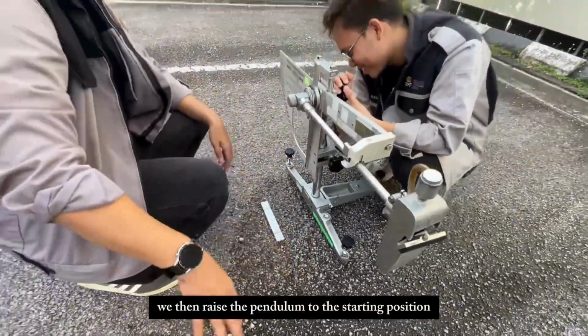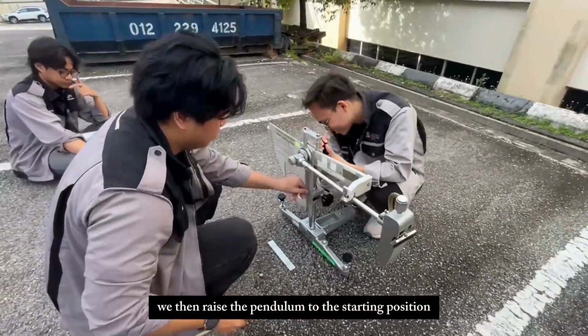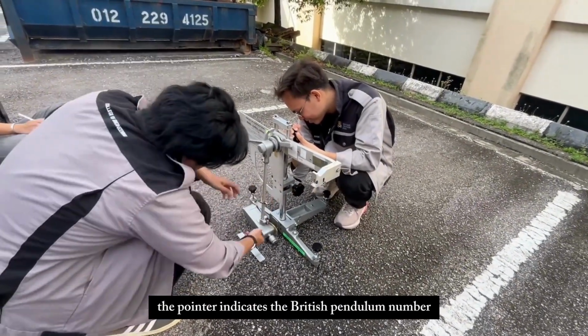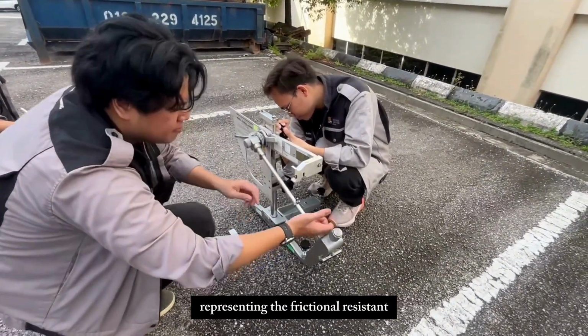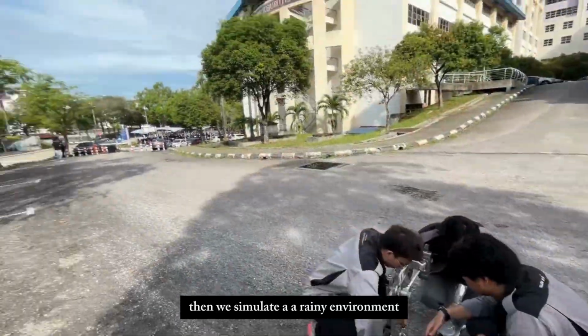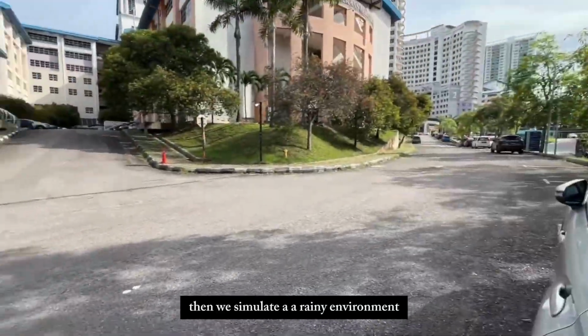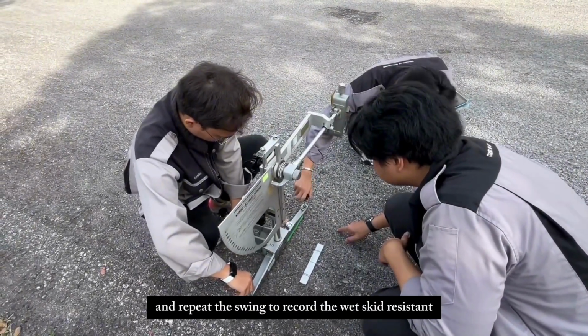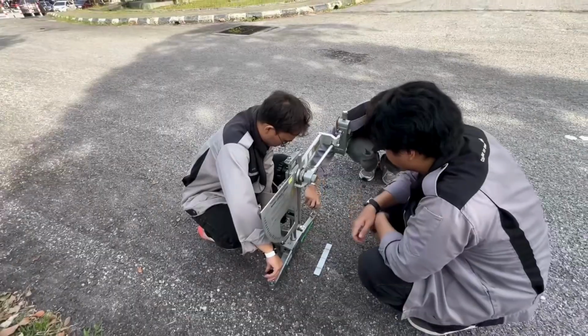We then raise the pendulum to the starting position and release it. The pointer indicates the British pendulum number, representing the frictional resistance. We record the readings under dry condition first, then we simulate a rainy environment by pouring water over the test area and repeat the swing to record the wet skid resistance.